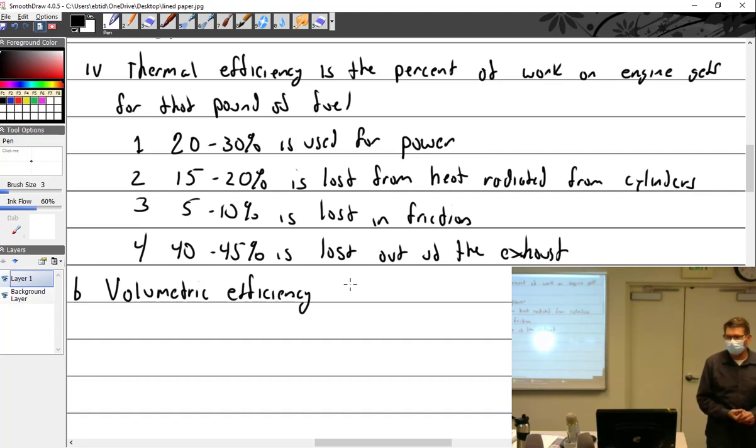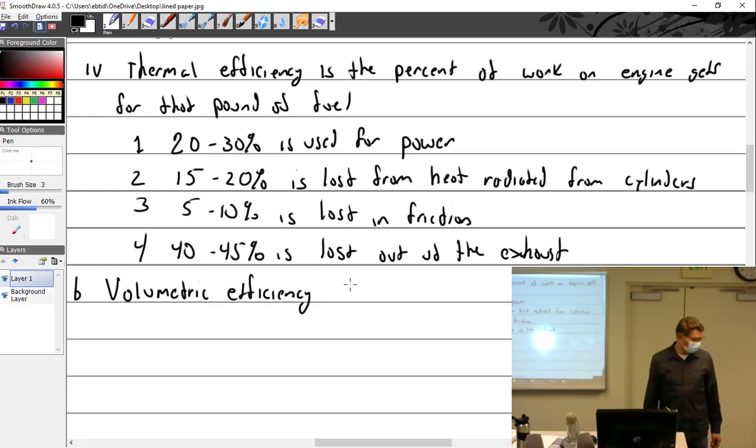The volumetric efficiency. If this is 50 cubic inches, when you measure cubic inches, what that really is, they use a liquid, and they take the piston and put it all the way at bottom dead center, fill it up full of liquid, and then put the piston on top dead center, and how much it pushed out is the displacement of the cylinder. That's where they get the 50 cubic inches. Everybody follow that? And then multiply it times how many cylinders there are. We spit out 50 and there's 4 cylinders, so it's roughly a 200 cubic inch engine. All right, that's how it works.